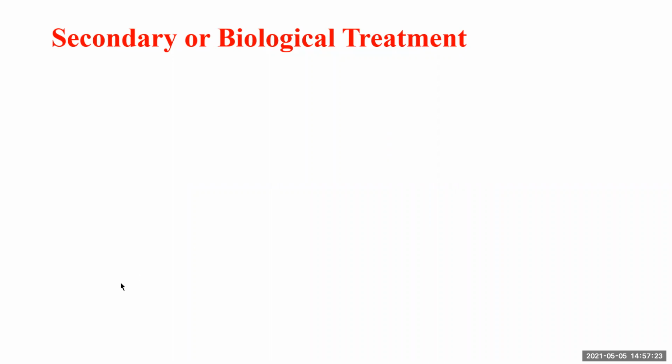In the last lecture, we studied wastewater treatment. Now, when we start wastewater treatment, the first thing we need to do is the preliminary treatment of the sewage. What does preliminary treatment involve? It involves removal of large objects like rags, plastic bags, papers, etc. That is screening, then grit removal, pre-aeration. That is followed by primary sewage treatment. Primary sewage treatment involves thickening and clarification, that is separating the solids and the liquid.